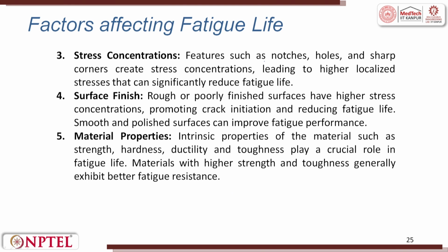Stress concentration means a feature like a notch, hole, or sharp corner creates a stress concentration, leading to higher localized stresses that can significantly reduce the fatigue life. That is why a hole is always made circular and not square. So, all these edges will be stress concentration points when you put this into fatigue loading.